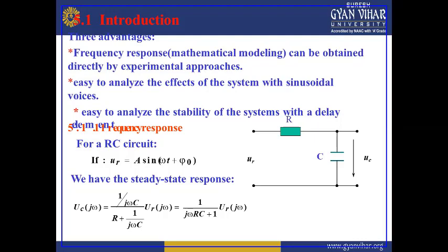Like in the previous lectures on time domain analysis, I taught you about time delays, where we have seen that in the step response, when we provide a delay, the system becomes quite sluggish and it is very difficult to analyze in the time domain. But in the frequency domain, it is comparatively easy to analyze the stability of the system with delay elements.